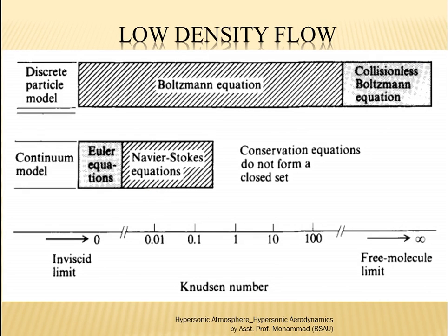So as I just now told, this is actually not depending upon the Mach number. In fact, Mach number is not playing any role here. It all depends upon the Knudsen number, which is the similarity parameter, which determines whether the regime will be the free molecule regime or the continuum regime. That will be totally determined by the Knudsen number. So this Knudsen number also depends upon two parameters: the mean free path and the characteristic length.